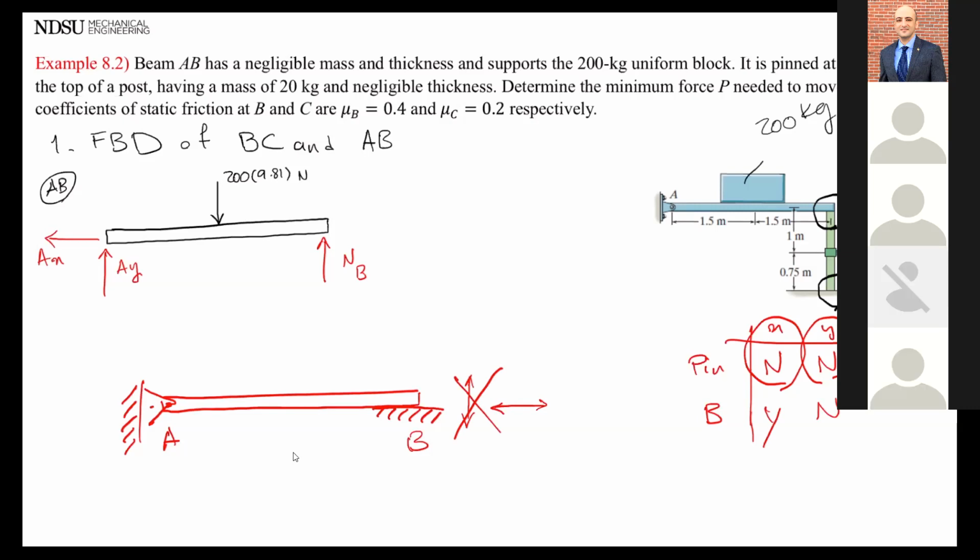Yes, it can. It's about whether it can or not, not whether it's supposed to. When you do that, you only look at point B. It can rotate. There's nothing on point B stopping it from rotation, right? So the only thing that we got to take care of is no. It's no different if it was a roller. It would result in the same free body diagram. It can move in X and Y. It cannot go up and down. It can rotate.